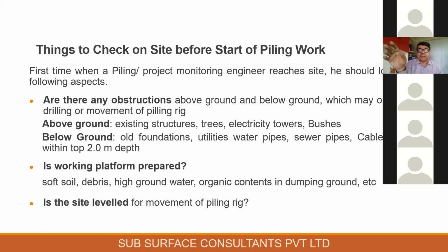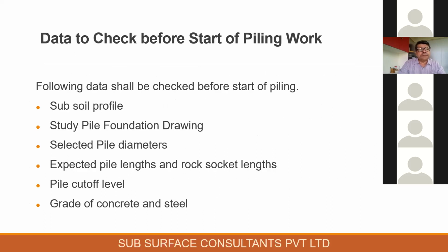And finally, is the site leveled for movement of the piling rig? It might appear superfluous to you, but for smooth movement of work, a firm working platform which is leveled is very important for carrying out the piling work. That will stop a lot of hassles during the progress of work, which are quite unnecessary. Let me go to the next slide.